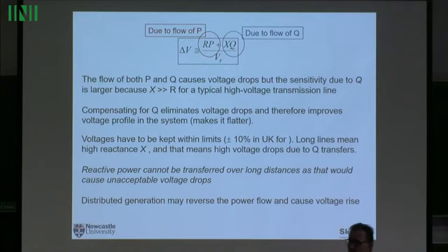So always two ways of compensation, remember. Either you have a capacitor, but then you need to invest money into it, or, it's far cheaper, you change the excitation current on the generator. It's a much cheaper way of doing it. Okay? Other questions?